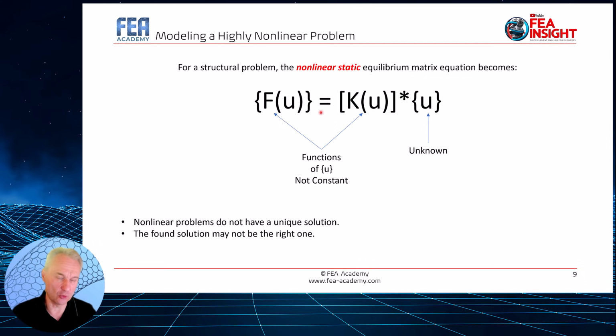The force equals stiffness times displacement. Force is a function of the displacement, and the stiffness is a function of the displacement. And for sure, the displacement is the unknown. It is what you are looking for, what you want to compute. So you understand the nature here of the nonlinearity. The structural stiffness matrix and possibly the load vector become functions of the displacement vector.